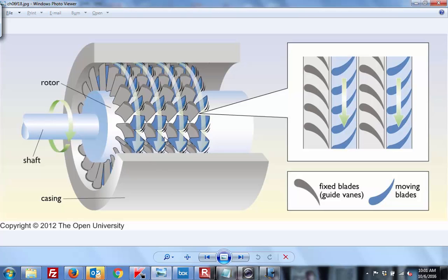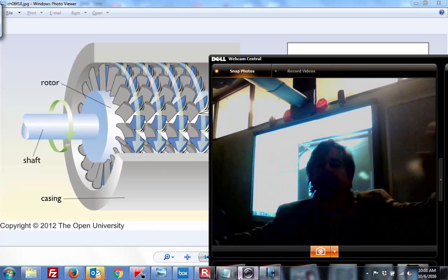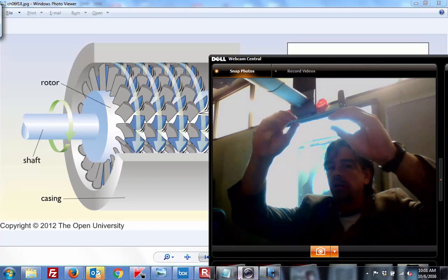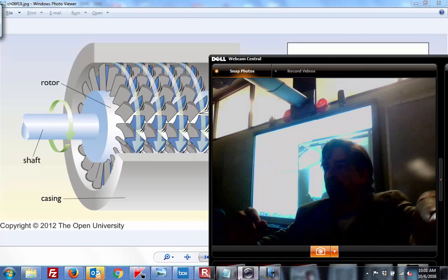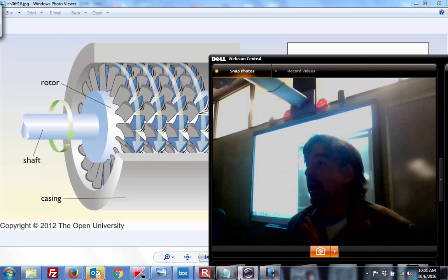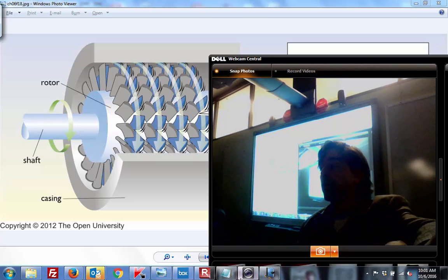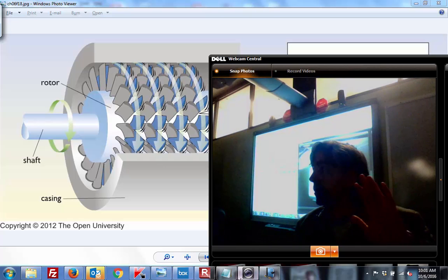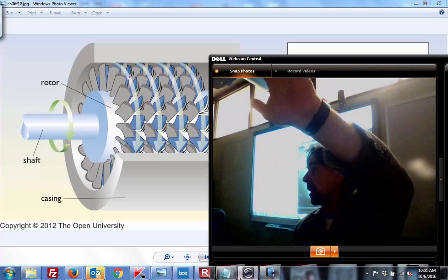I was not doing this work myself, but there were some really very talented mechanical engineers there at the University of Michigan that were looking at creep. So in mechanical engineering, any material that's stretching. So you can imagine as this blade is spinning, spin your arm in a circle, all the blood rushes out to the end of your hand. Same thing going on here. It's a merry-go-round doing several thousand RPMs. The engine literally wants to tear itself apart. Those blades want to go flying out through that outer casing.